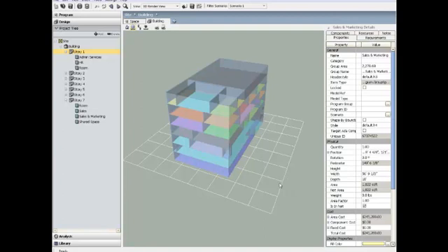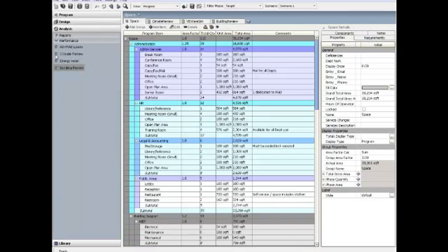Now we have a program that contains additional data specific to VE, as well as a stacked building that contains the departments in our program, which means we are ready to move forward with the VE analyses. A selection of VE Gaia analyses are embedded within Affinity, so we can run them directly without having to open the VE desktop. First, let's take a look at the climate review.